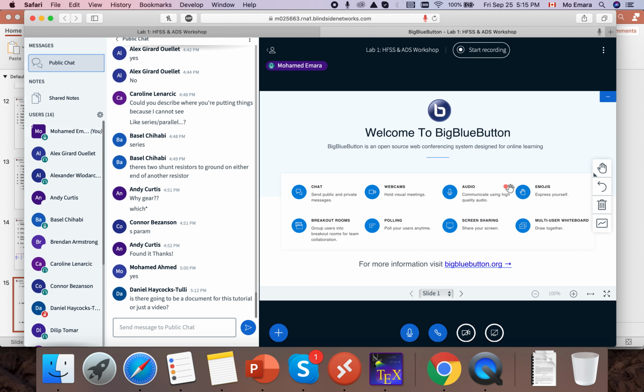ADS would be good if you're designing amplifiers, attenuators, any sort of circuit where the only electromagnetics really is just the connections between the components. So if you have a circuit on a PCB, and you have a bunch of components, amplifiers, regulators, and the only electromagnetics is connecting all these components together, so the only electromagnetics really is the transmission lines, then you can use ADS with confidence, because it has very good approximations for the responses of transmission lines using those analytical formulas I was talking about.